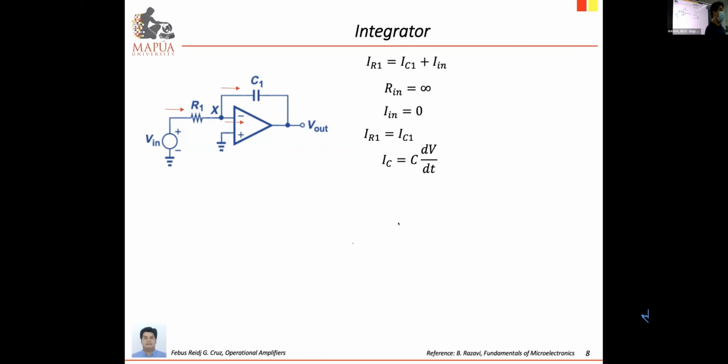Alright, so whenever you have capacitor in your circuit, the voltage will not suddenly increase or instantaneously decrease. It will introduce a certain time delay. It will take time to charge or to accumulate voltage. And the third basic passive device, you have the inductor. Basic function of inductor is to oppose change in current. All right, so again, resistor opposes current, capacitor opposes change in voltage, that is delta V over delta t. All right, then inductor opposes change in current.